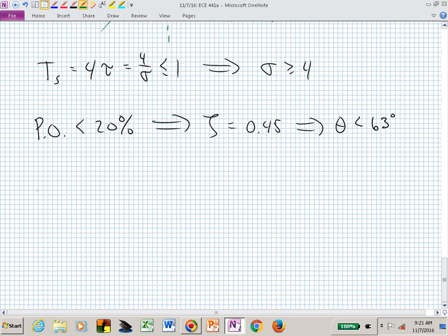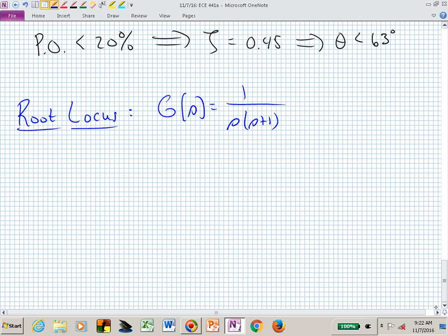What's the root locus of G of s look like? And now you should actually be almost instantly sketching that mentally. But if we are not, what's my pole zero excess? 2. So now do I have some interesting asymptotes? When I say interesting, I'm meaning something other than 180. 180 is sort of boring. That's going off to minus infinity. But in this case, we do have 2 asymptotes.